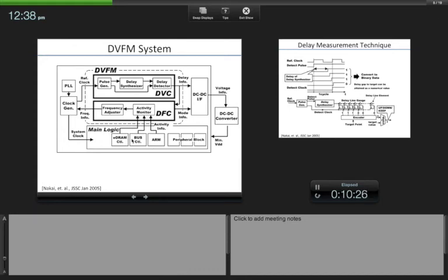Similarly, bus control. There will be a bus on which all the components in the SoC are connected to. Anyone who wants to access the bus has to make a request, right? That request will go to a bus controller, which is essentially an arbiter, because multiple people want to use the bus. So the arbiter of the bus controller will decide whom to give access of the bus. So again, there you have visibility on the activity of the bus.